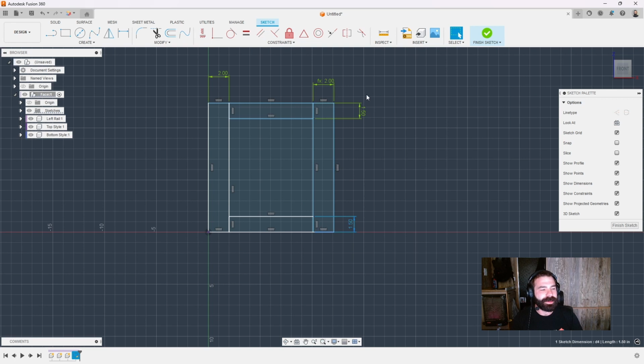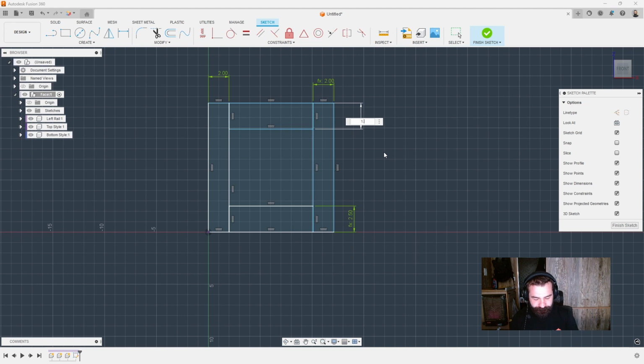Again, if I want this dimension and this dimension always the same, I could use an equals constraint. However, I found it's better just to be able to click that first dimension to cut down on how many dimensions I have showing up. And again, if we went to a 2.5 outline, both update automatically. Let's go ahead and put that to 1.5.